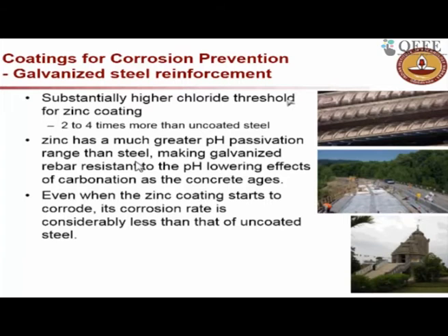So that's one advantage of this. In other words, you are increasing the chloride threshold by 2 to 4 times. Okay. Now also, zinc has a very wide passivation range, or in other words, for a wide range of pH the zinc will not corrode.